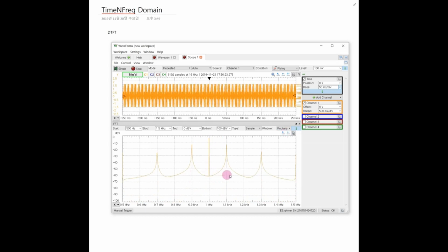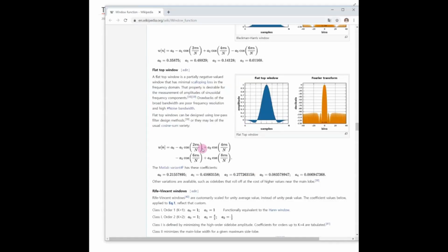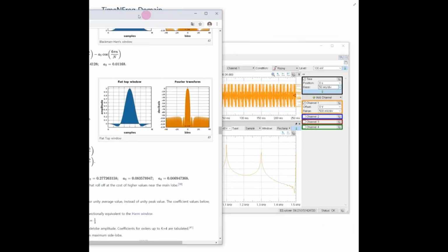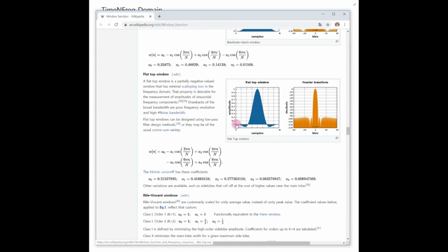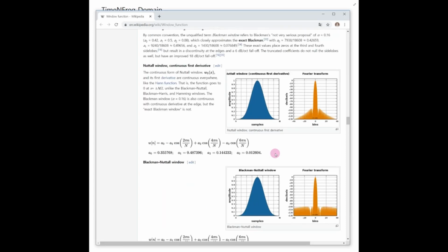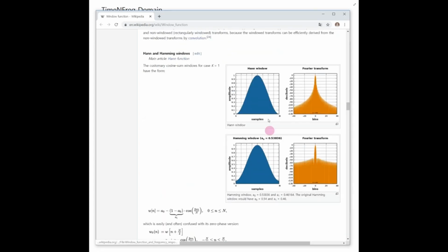The spectral shapes are changing depending on the window. I talk about that window effect over here. So I talk about the flat top window. This is the flat top window. If I take this window, the periodic boundary is converged to 0. If I take the Hanning window or Hamming window, it looks like this one. So the Hanning window is almost 0. For the Hamming window, there is still some residual at the periodic boundary.